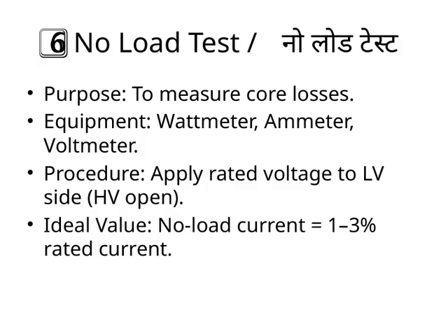This small current indicates the magnetizing current required to establish the magnetic flux in the core. Understanding this helps us assess the efficiency of the transformer and identify any related issues. So, this test is a fundamental part of transformer testing, giving us insight into the core's behavior under no-load conditions.